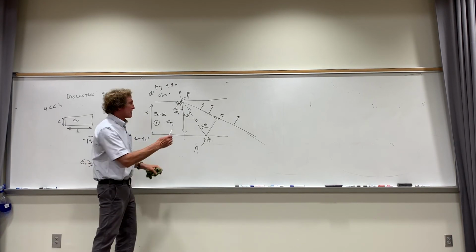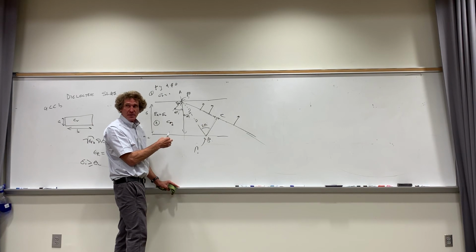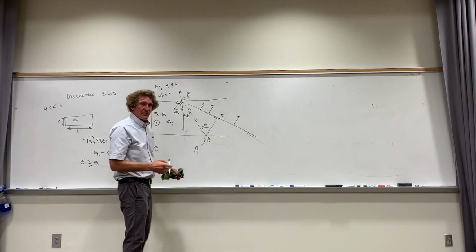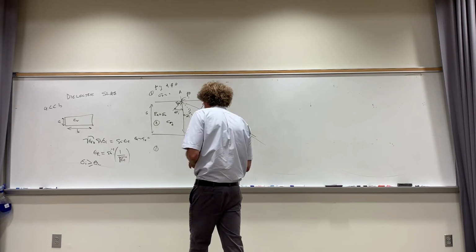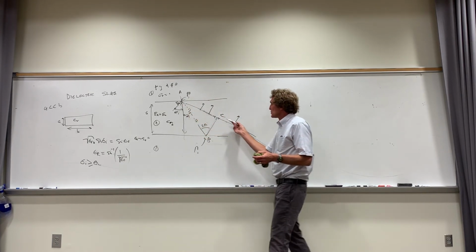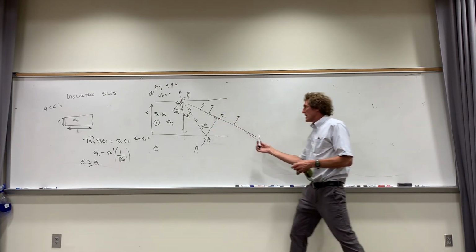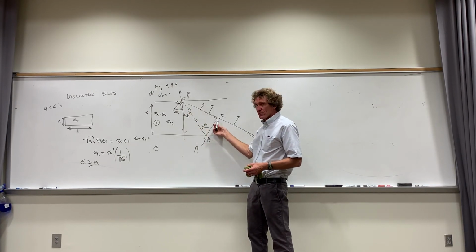That means I can't have a mode where I slam it straight up and down, because what will happen is some of that's going to be transmitted and the thing will die down. But if you're at that angle or higher, then everything bounces in between that waveguide. Everybody understand that? Now the way we get the modes is this, and this isn't something you're going to like, but we have to say that there's an assumed wavefront, that these waves are banging this way and that way. And there has to be coherency, or this one bouncing down here, coming up to that wavefront here has to be the same phase.